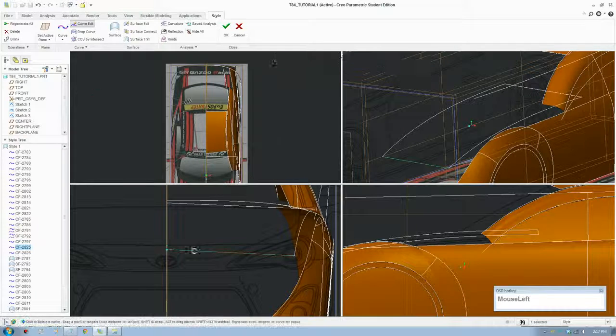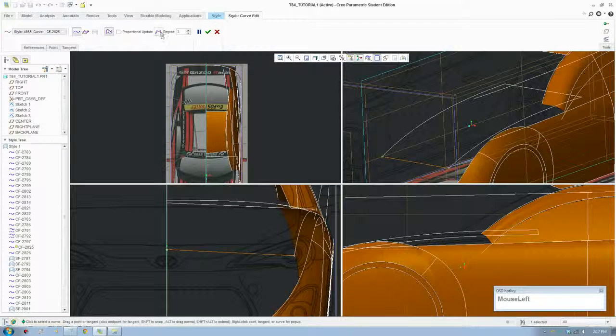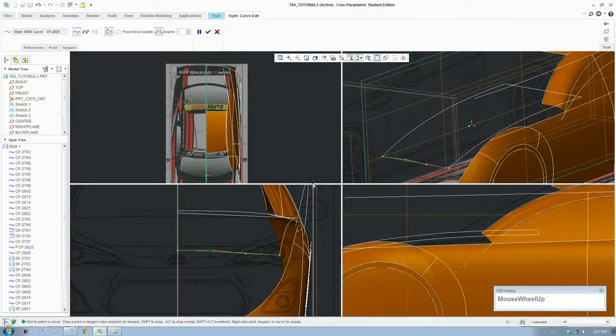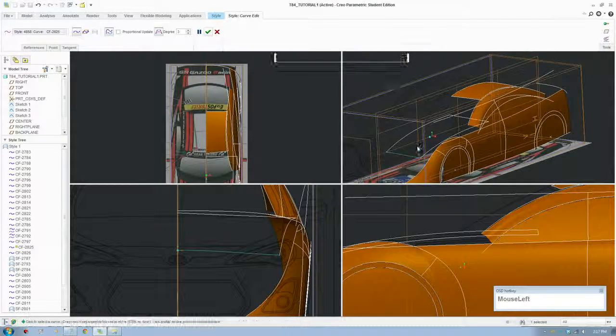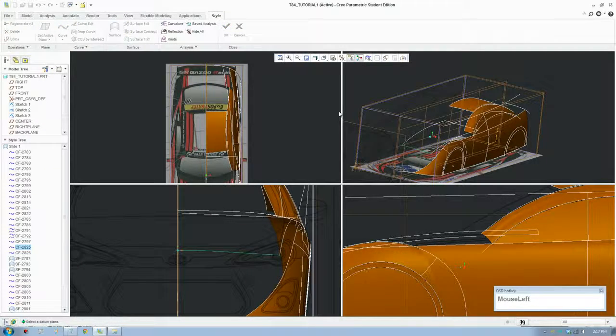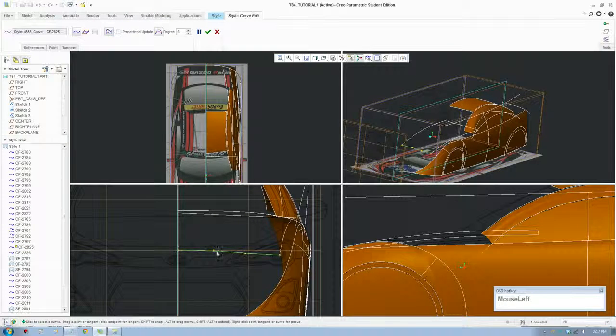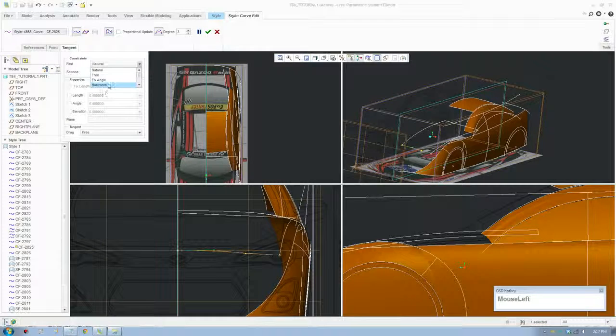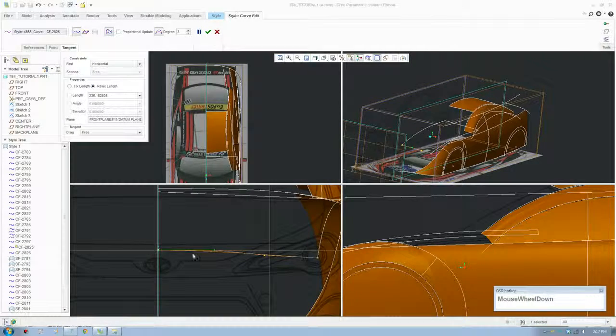And we gotta make sure this is tangent with the mirror view. We make sure it's horizontal with the points. So we're going to activate one of the appropriate views, and we'll go edit, click on the point, go to tangency, make that horizontal, and see this point and that point, it's in line.